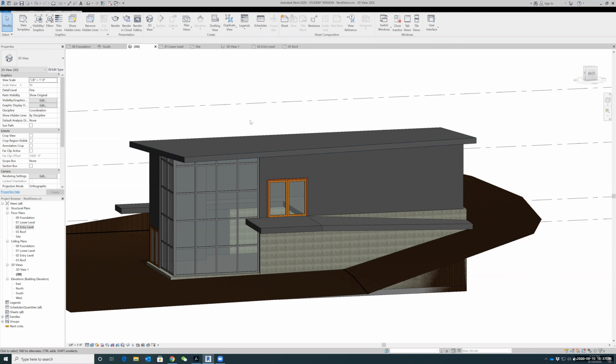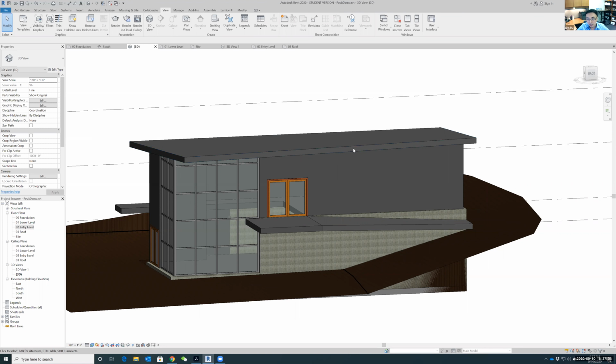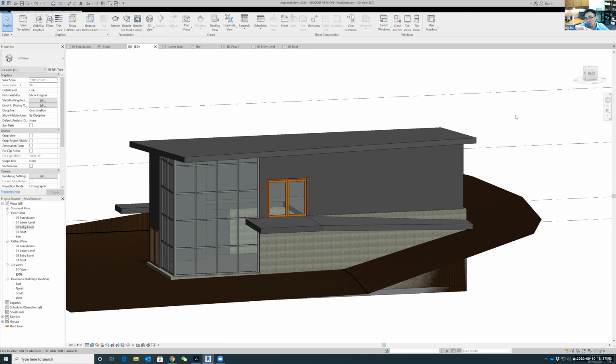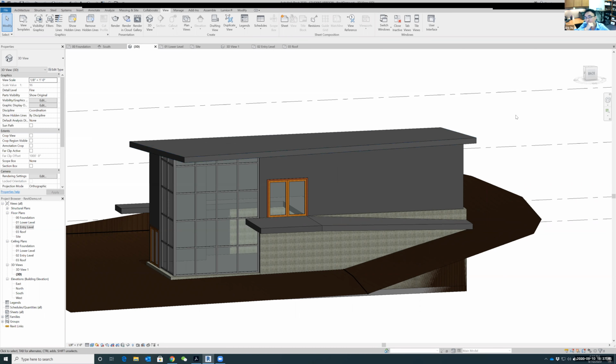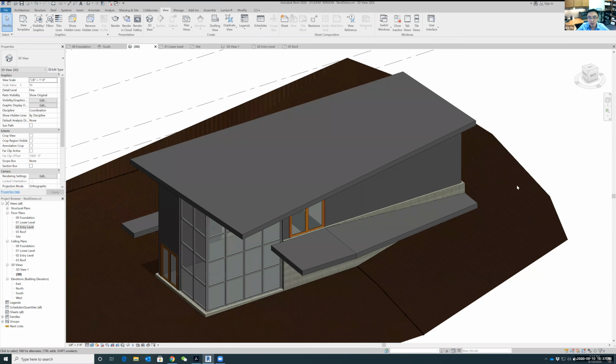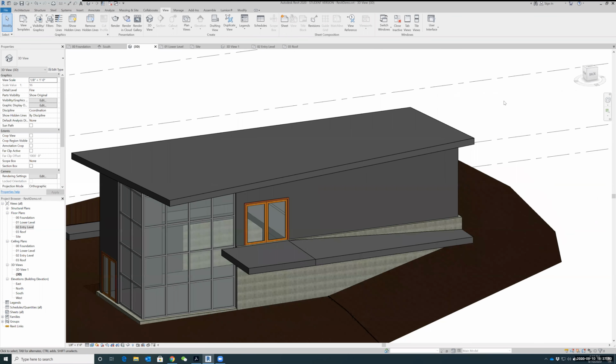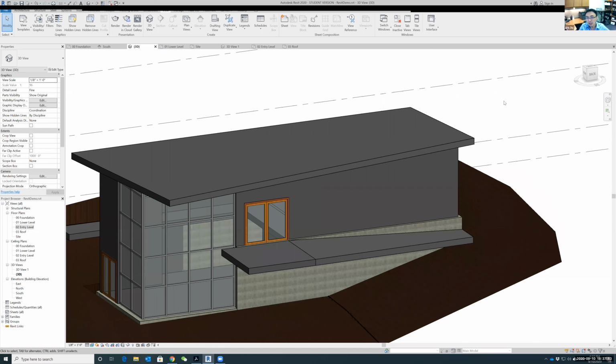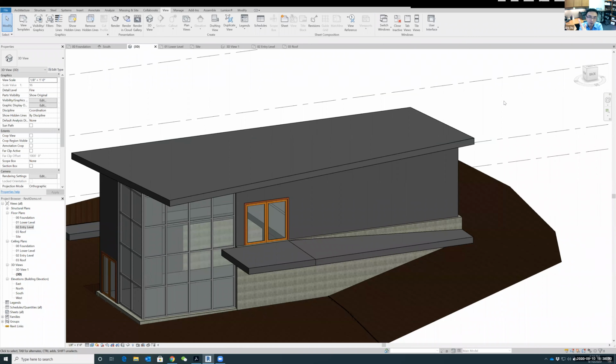Just to confirm, we skipped step 12, right? Yes. Step 12 is about how to edit the boundary of a finished floor or roof or something. I just showed you a quick example of how we change the boundary of the roof. The entire thing about step 12 is, you have a very complex relationship between the wall and the floor, so how you can replot all the boundary lines to go over all the walls. It's just a time consuming piece of work, but it's not that much new.